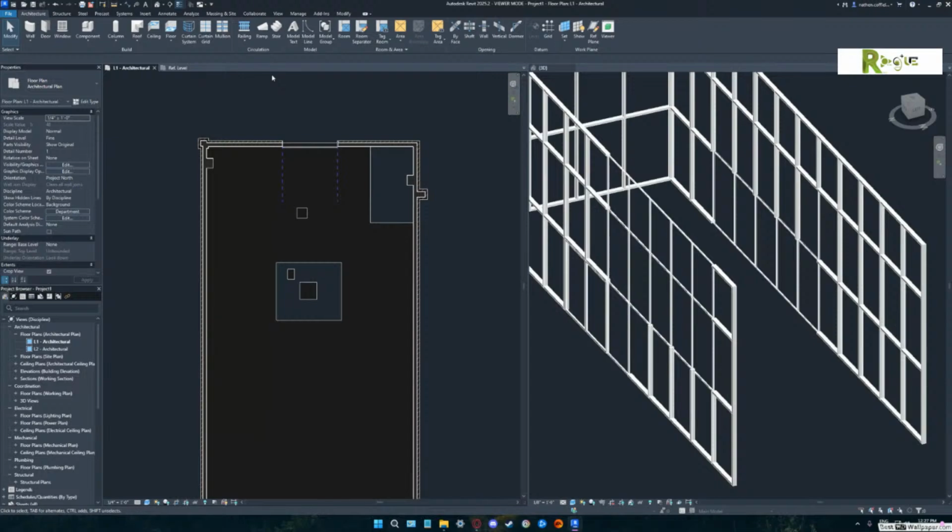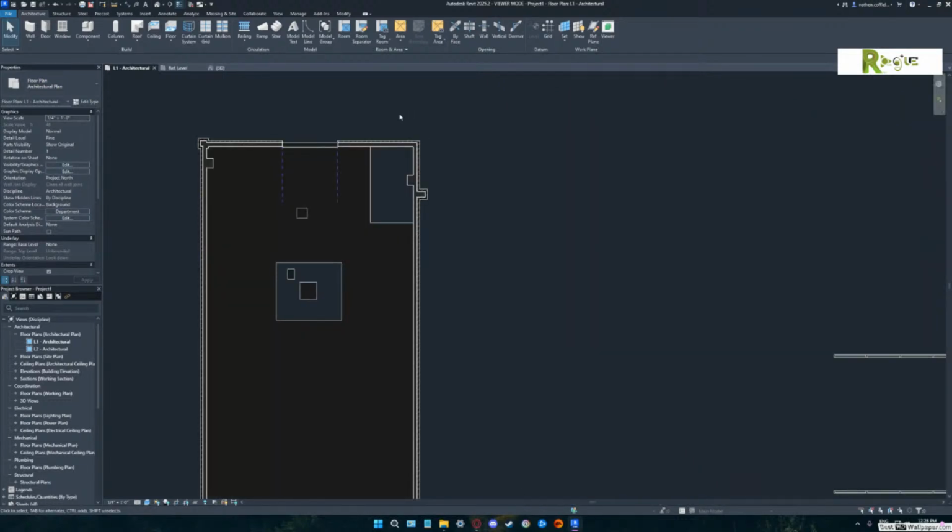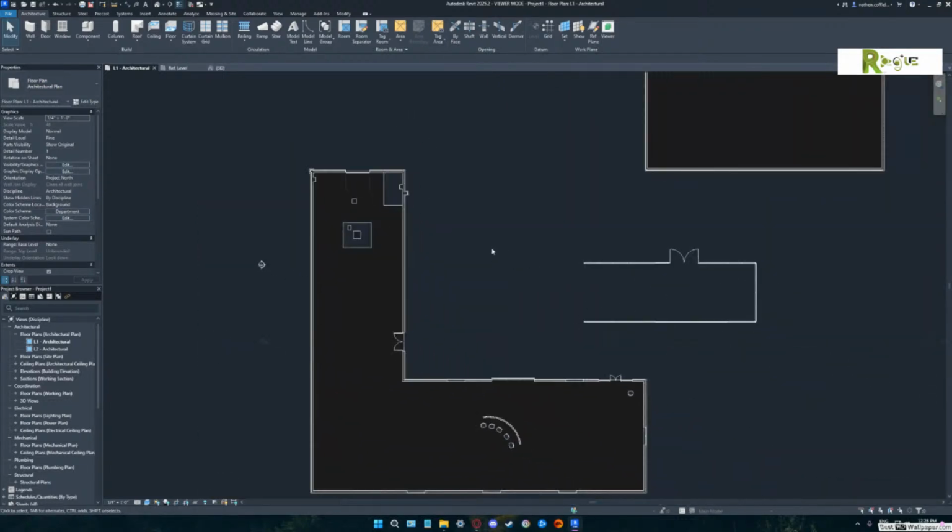Now, if you're going to add a stair, where's your stair going to go if all you have is a single floor, right? Your job is just a single floor right now, correct? Yeah. All right, so zoom out in your plan view. As a matter of fact, let's just type in TW. Last time I told you WT, which is window tile, and that makes you have split screen. Now I'm telling you do TW, and that'll get rid of your split screen.